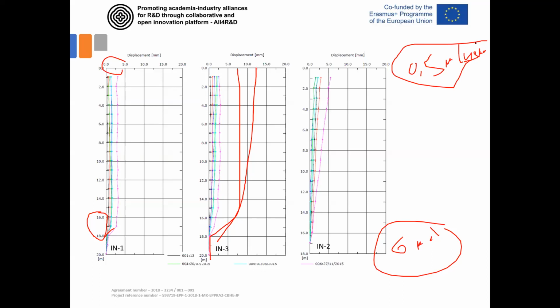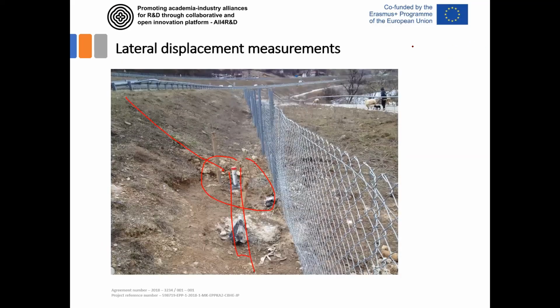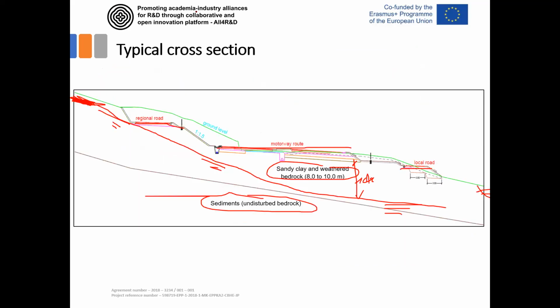Of course, some preliminary designs were performed, but it showed that really a lot of effort, money, and energy must be performed to stop any sliding in this area. So there are actually two designs for this slope. One is a so-called group of just a preliminary measure to reduce the probability of sliding, and that consists of construction of sub-horizontal drains in this area.